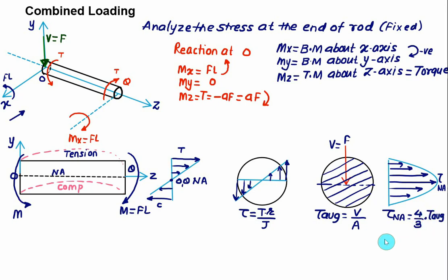So three stresses you have to study for the given loading. One is the bending stress, then we have the shear stress due to torsion, and then we have the shear stress due to the transverse shear force.